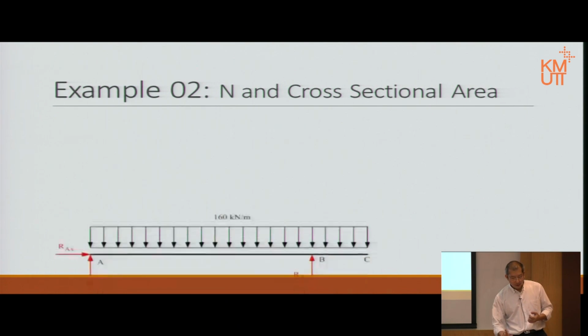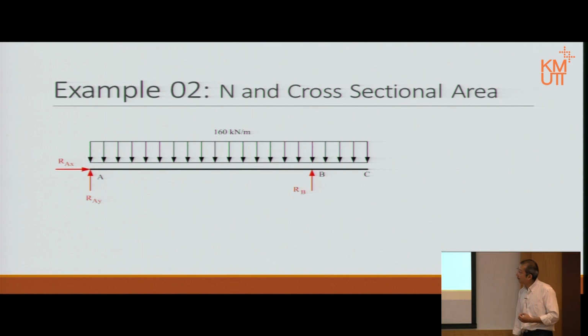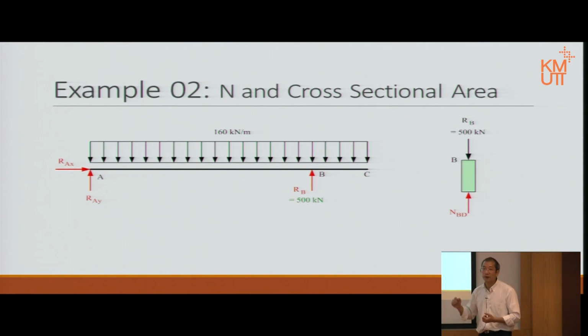Okay, so let's go determine axial force. The free body diagram. That one there will be RB, that one will be connecting to the column BD, right? Action reaction. If column BD pushes the beam by RB, then the beam will push the column downwards, opposite, equal to RB as well. So if we calculate that, take moment about point A, we get RB straight away, apply that to the column, and then find out the internal force, axial force for BD.